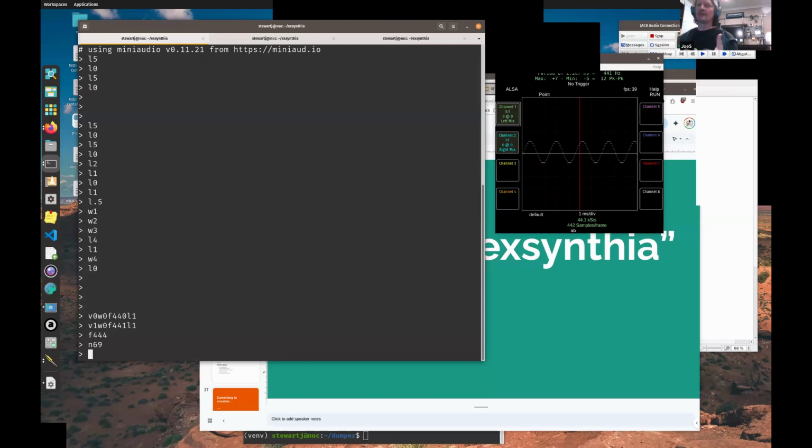The idea here is that this is just adopting the MIDI wire protocol notation. They do the same thing. But this makes it so that if you're trying to map keyboard presses from a MIDI device into this, there's a little less math that you would have to do. An interesting thing that MIDI does not support, though, but I do, is if I type 69.1, it can understand fractional numbers, where MIDI absolutely does not. It's a 7-bit note number that's used inside MIDI.